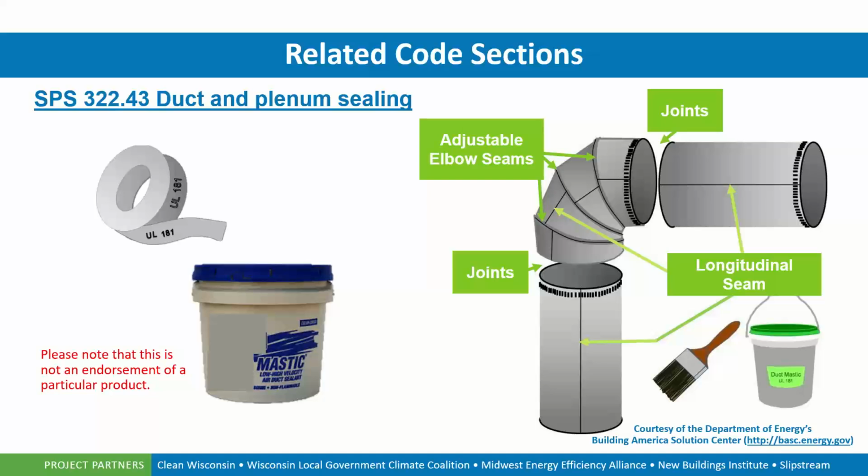The application of mastic, typically over time, I've always referred to it as being approximately the thickness of a nickel to achieve the best sealing possible. And it doesn't have to be more than just half a brush width across that seam. We're not going for complete coverage of the duct, just making sure that this seam is sealed. So again, especially when we have elbows, there are a lot of seams within a metal duct elbow that need to be properly sealed off.